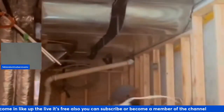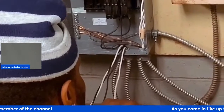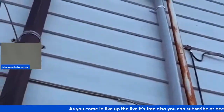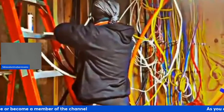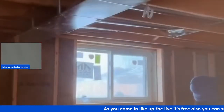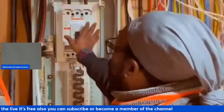an arc fault. There's something called a dead front. We use it a lot. You can basically put that at the beginning of the circuit outside of the panel. It's going to protect it also. Or if you run your aluminum cable to the location, you can simply put it on a regular breaker and then have the GFCI arc fault in that location, where it's not really a full-size kitchen, and that's how we go around that scenario.